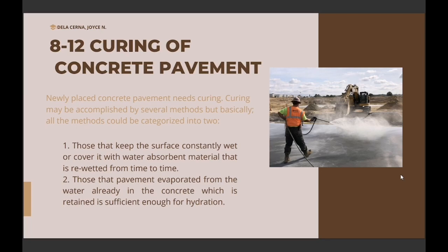Number two is those that prevent evaporation, so the water already in the concrete is retained and is sufficient for hydration. Curing is a treatment or protection of concrete during its hardening period. It is providing adequate moisture, temperature, and time to allow the concrete to achieve the desired properties for its intended use. So how many days is curing of concrete?